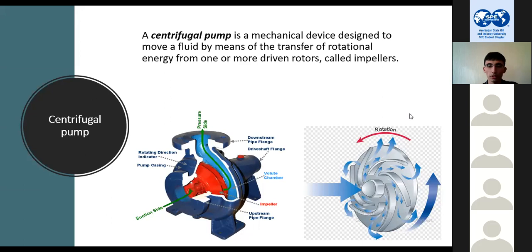Again, I'm trying not to go into the details. Like with centrifugal pumps, you should be careful with something called NPSH. You have to always keep your NPSH available more than your NPSH required, or you can experience something called cavitation.